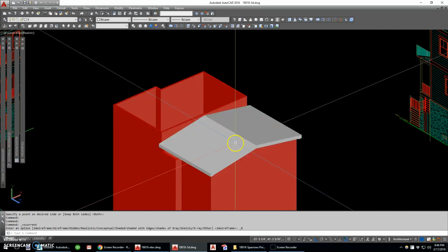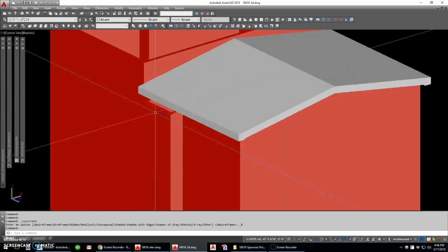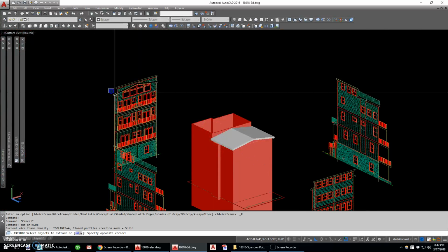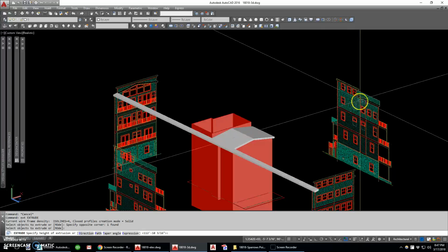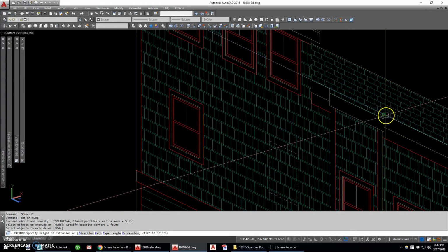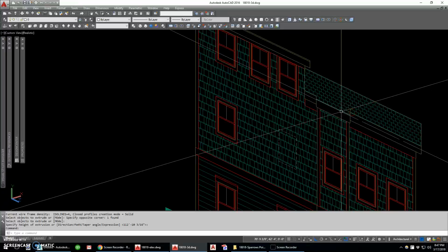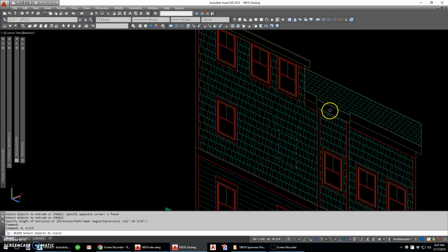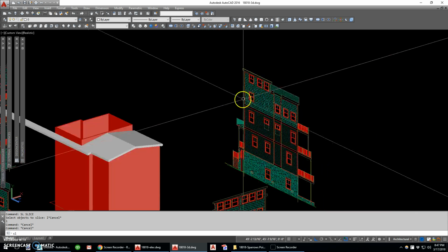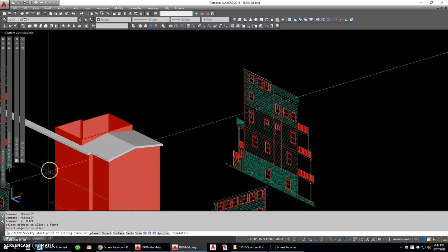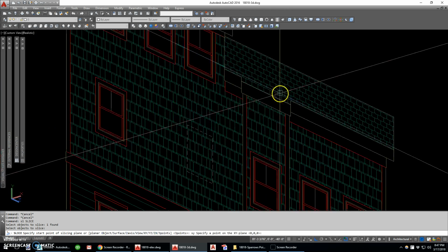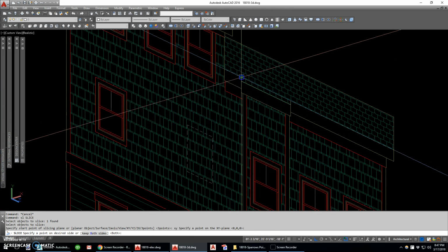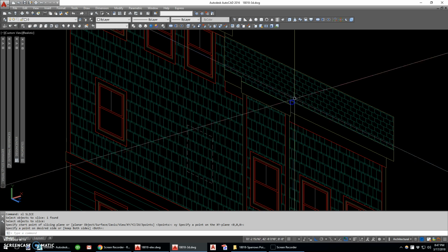If I do this in 3D, great, that roof's done, but I still need to do this little roof while I'm there. So I'm going to go ahead and extrude that polyline, use my elevation as a reference, and without even looking at it, I'm going to slice. I'm going to type L for my last object. We lock up here. What's going on? Let me escape and try that again. I'm going to slice this. I'm going to type XY for my XY plane. I'm going to use my elevation for a reference and pick the side I want to keep.